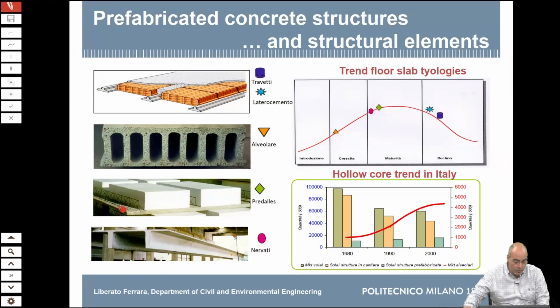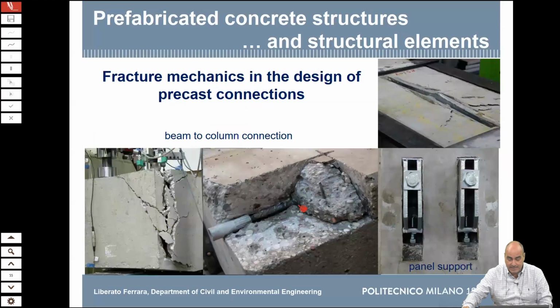Nowadays, for new construction, the most common form of slabs is either with precast elements or with predalle, in which you precast the bottom slabs, and there are these steel trusses, and these are polystyrene blocks which perform both the function of lessening the weight and providing some insulation, and we complete with some cast-in-place casting.